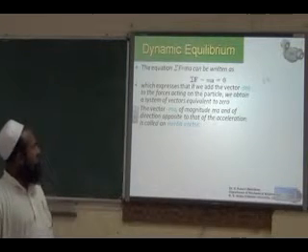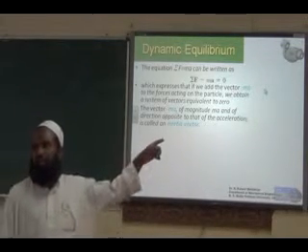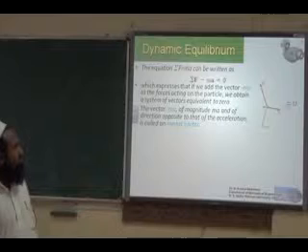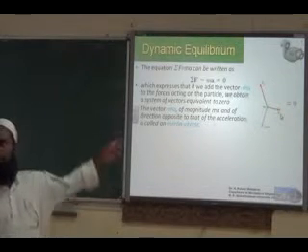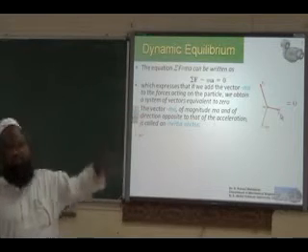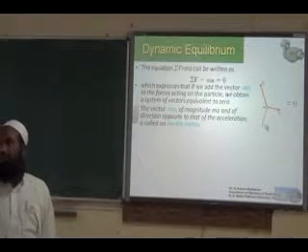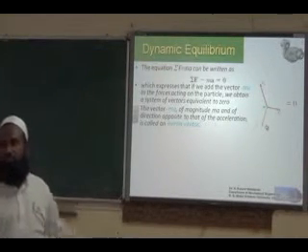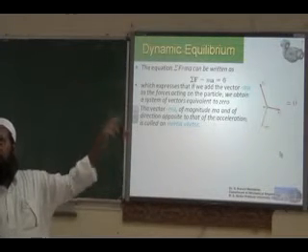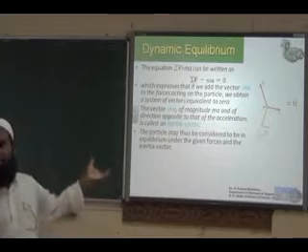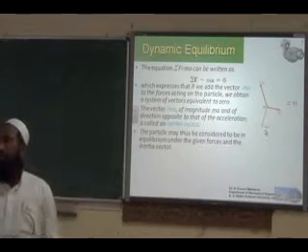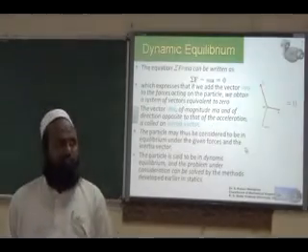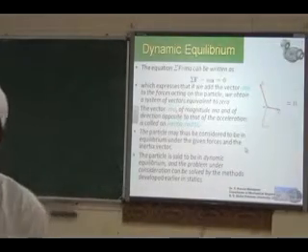So this minus ma is called the inertia vector. The minus ma is actually the internal force. So you have forces F1, F2, there are many forces, each will have their resultant force. Then minus ma. So sigma F, all the external forces plus this internal force minus ma, equals 0. This will bring your system to dynamic equilibrium. So we convert a dynamic system similar to a static system by using this equation and we can solve it. So the dynamic system can be modeled as a static system and we can solve it.